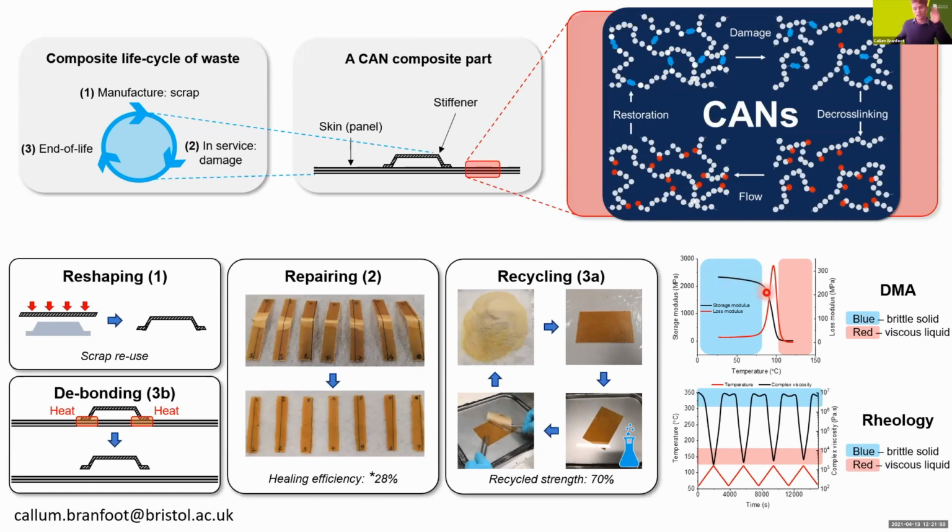And then when it is heated, in this case, as the stimulus, it decrosslinks around 100, 120 degrees, and what you end up with is a viscous liquid. If we repeat this process many times, as shown by the cyclical rheology here, decrosslinking, recrosslinking, and so on, therein is the value here.